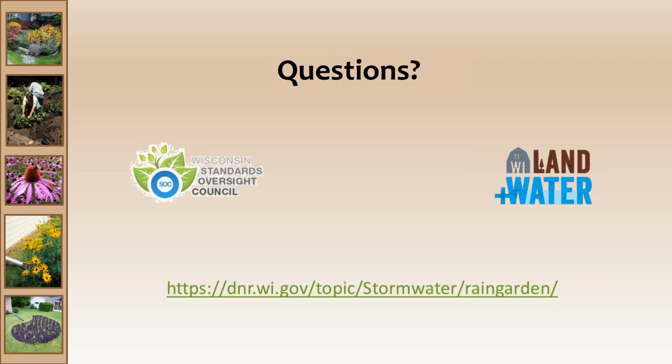Yeah. Native plants do not need high quality soil when you're digging the rain garden and you're getting into more porous soils on the bottom. I was saying that if you're going to plant turf, you might want to save a lot of topsoil and reapply it at a significant depth. But if you're planting natives, they don't need that much, just a little bit of growing medium. Do you agree, Roger? I agree.